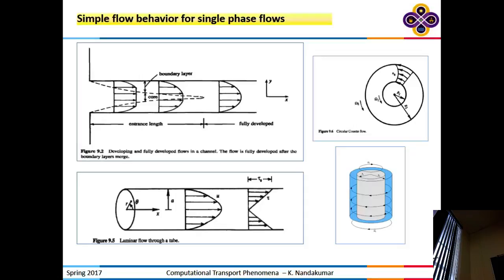Where is the force that causes the y direction? The wall, the actual wall. So the reduction in speed constantly. That's the key. The reduction in speed. Like if I integrate this, I will get a flow rate, right? But if I go ahead and integrate this one, that flow rate must be the same. Mass is conserved. Every line, the flow rate must be the same, right? And that means that the velocity here must increase because the velocity here has decreased. And if the velocity here decreased, where did the flow go? Escapes into the upward flow, right?